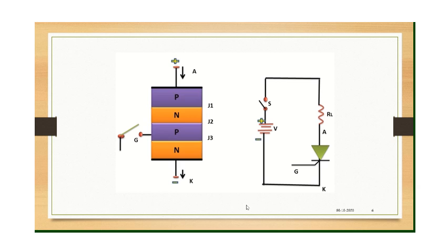One is, say you have this circuit where you have connected this V across anode and cathode terminal, you have the load. Say if you have a simple switch in the circuit, if you just open the switch, you can make the anode current reduce to zero, right? Or the other way is you increase the impedance of the load.